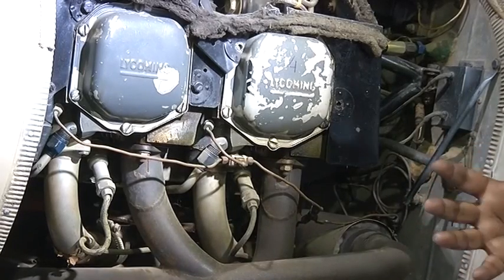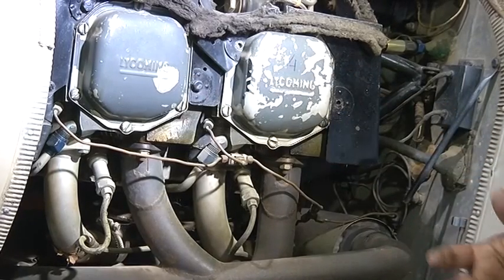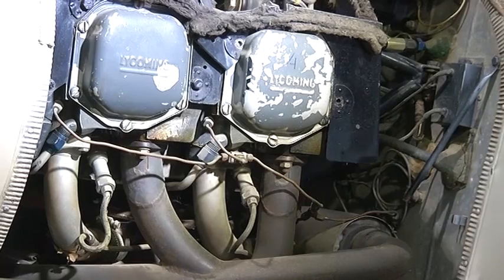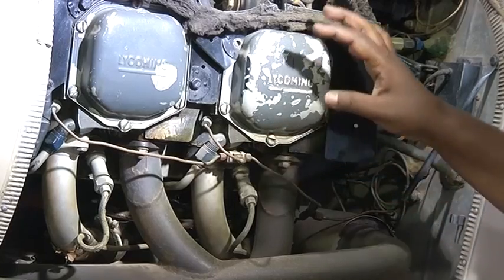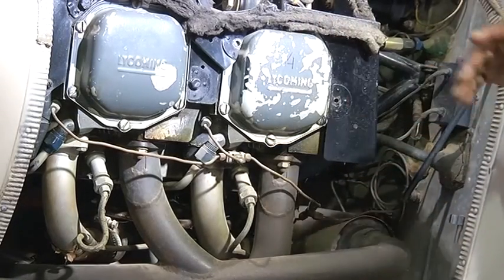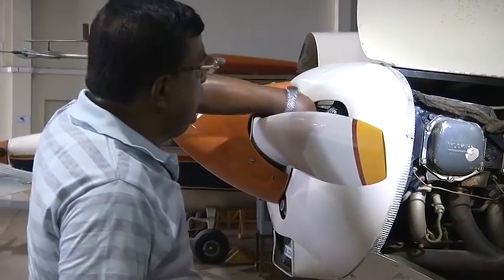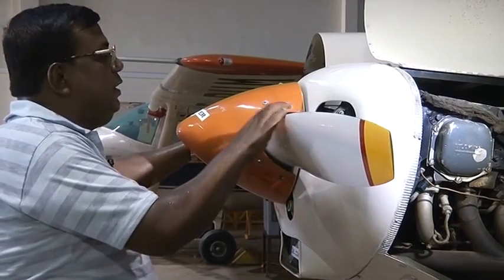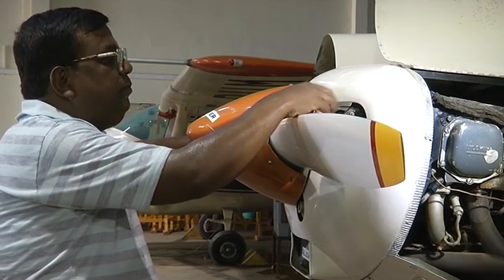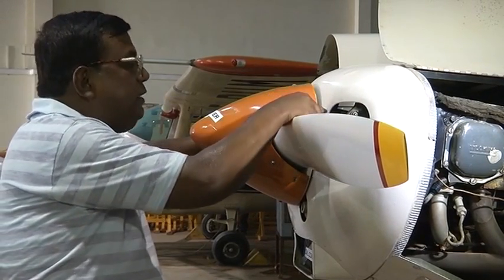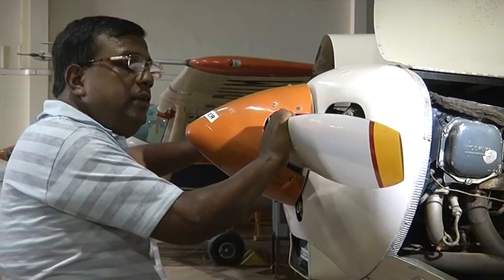The only difference between car, motorcycle and aircraft engines is the number of cylinders, which may be 4, 6, or 8, because we need more power, right? But let us not forget the basics. The fuel is burnt in the cylinder, which drives the piston, and the piston then rotates the crankshaft. The crankshaft is somewhere here. You see here, the shaft is here, and there is a propeller mounted on the crankshaft. Whatever energy is burnt in the fuel in the cylinder delivers power at the crankshaft, and when I attach a propeller, the propeller draws that power, but the propeller has its own efficiency.